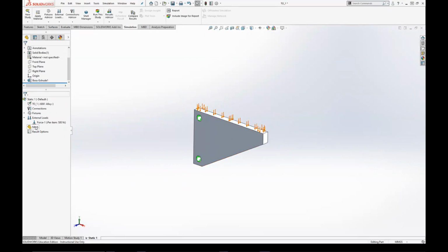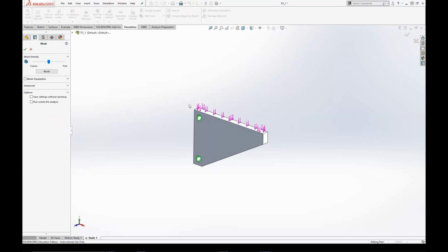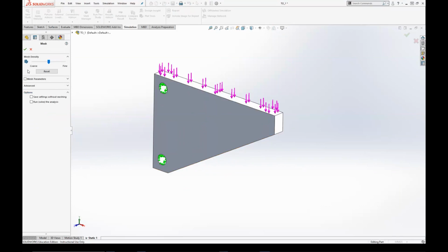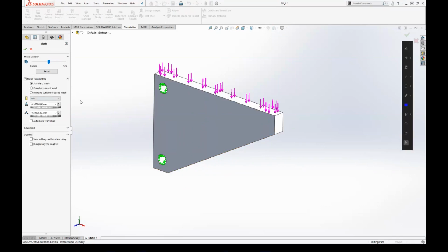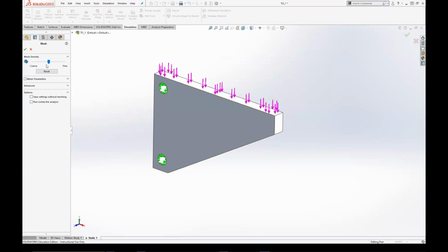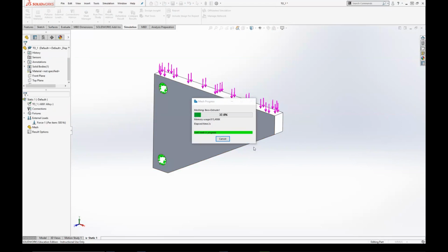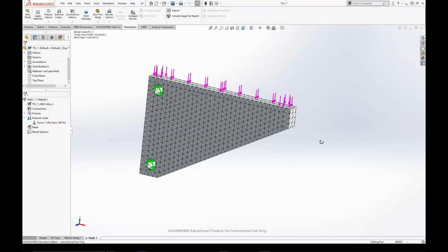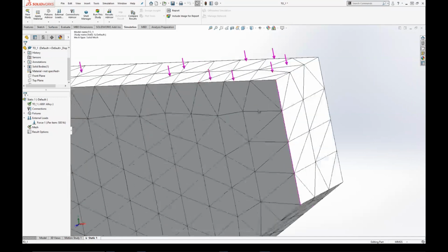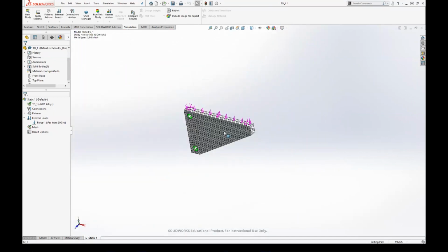This is where I explained converting the part into discrete small elements. Okay. Finite elements. Here I am going to create a mesh part. If you see, I am going to create a mesh out of it. There are actually advanced controls for mesh also, but I'm not going to explain that in detail. So I'm going to create a mesh somewhere in between coarse and fine. So I am clicking OK. Now the part has been cut into small triangular meshes.